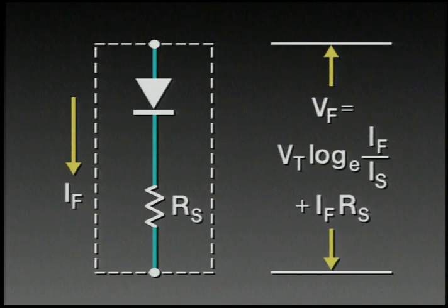Now, so far we've assumed the junctions are perfect. One of the first things that can go wrong with a practical junction is that it has associated with it some series resistance. In the case of a real two-terminal diode, this resistance can be quite troublesome because it's often very considerable. It represents the ohmic resistance of those portions of the junction leading up to the active region. So the forward voltage is the sum of the logarithmic component and a linear ohmic component, I_F times R sub S.